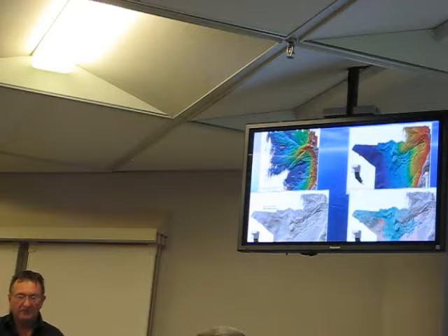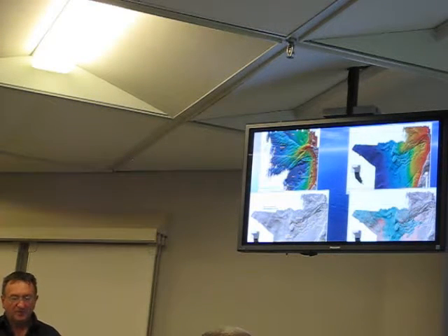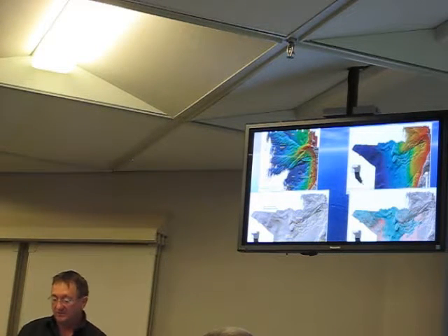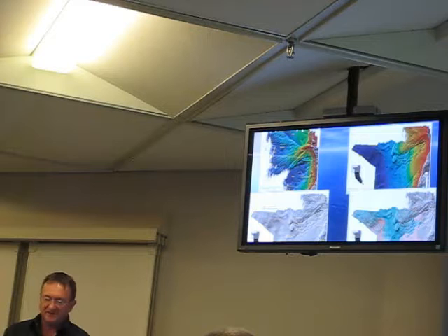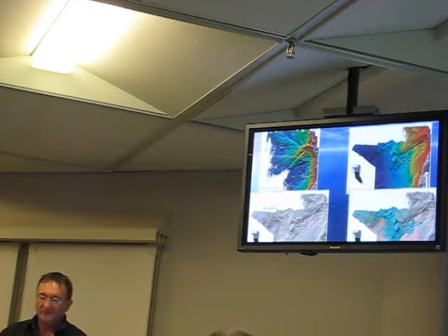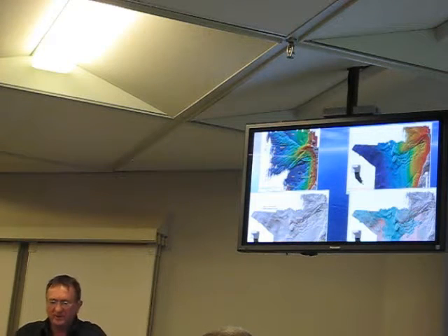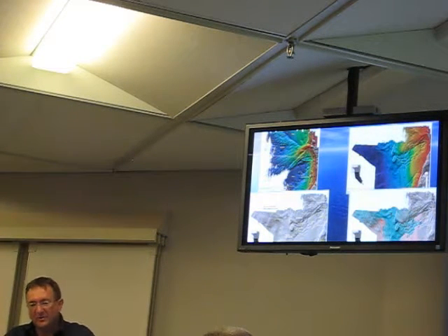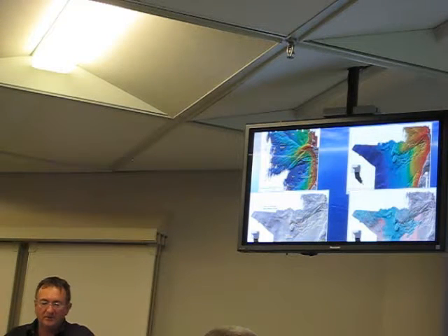It's very critical to ensure a good comparison of the data sets, to use similar or the same positioning systems, and in particular vertical control. For our surveys, everything was referenced to the ellipsoid, so the horizontal positions were, of course, but in particular the vertical was, so we got height above the ellipsoid for all the LiDAR points.